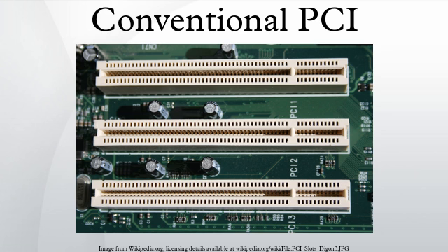0011, I/O write. This performs a write to I/O space. 010X, reserved. A PCI device must not respond to an address cycle with these command codes.